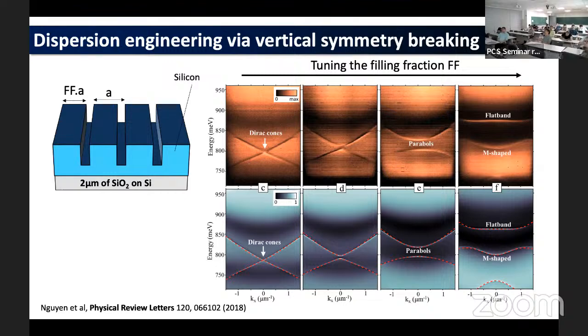And the thickness is about 400, 500 nanometers. Because if you want to have the single mode, it is 200 nanometers, but here we have the bimodal case, so we need to double. Roughly speaking, I don't have the exact value in mind.